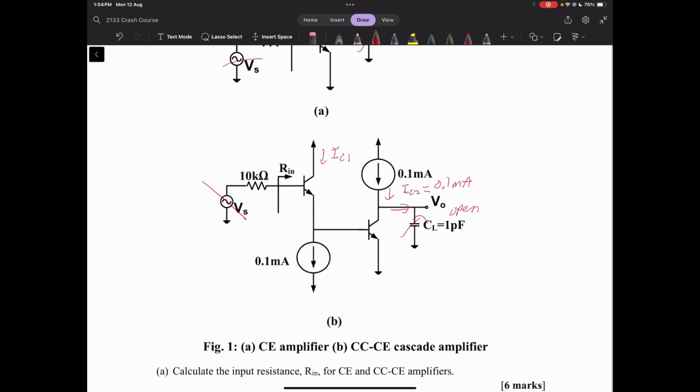This is a bit more difficult because we don't have a DC source up here just telling us what the current will be when we do our DC analysis. But one thing you might know is that IC is going to equal beta IB, and beta in this case is equal to 100, which means that IB is 1/100th of IC, which is quite small.